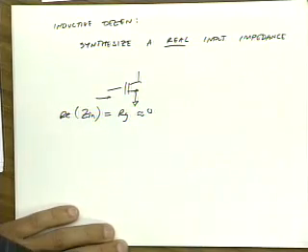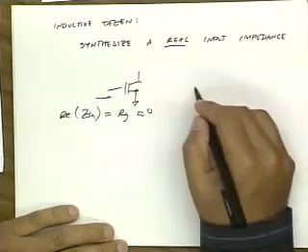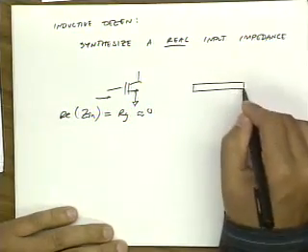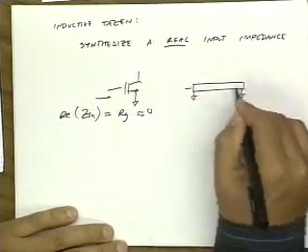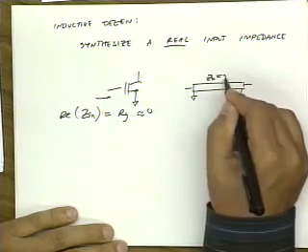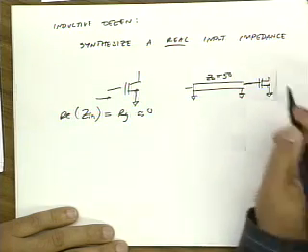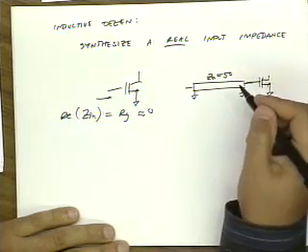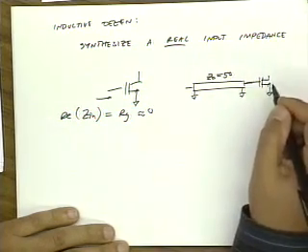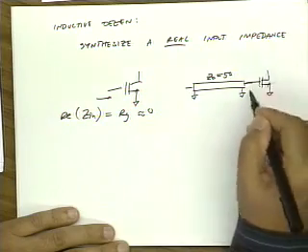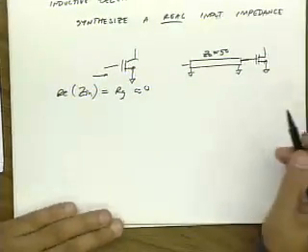And let's say I want to drive this with a 50 ohm source resistance. Let's say I have a cable or a transmission line which has a Z0 of 50 ohms, and I want my transistor to terminate this with 50 ohms. Well, that's pretty hard to do with the transistor. A transistor on its own is going to look like a capacitive termination.